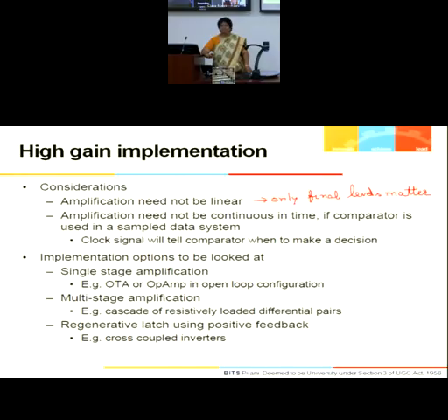So here, a very good use of analog sampled systems can be made, where you are using switches to perform 3 different operations, and output will come after 3 different operations. These operations come because of turning on and turning off of different switches. So you can have different phases of clock which are controlling these switches. You control the phases of the clock.